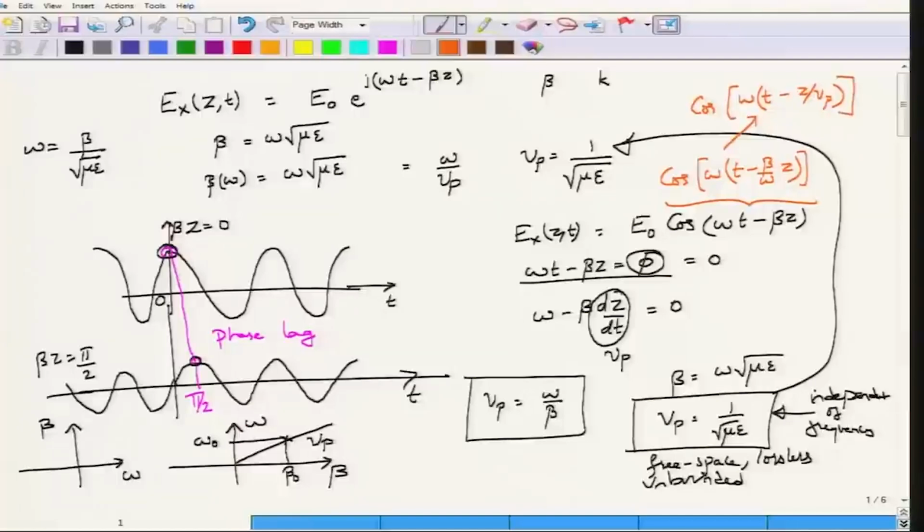This clearly indicates a travelling waveform with respect to time, but its phase velocity is Vp. If you remember your physics classes, this would be the wave equation for a wave that is propagating, having a frequency omega, having a velocity. At that point it was not specified what velocity you were considering, but this is actually the phase velocity. So, it is clear that the phase velocity happens to be independent of the frequency, and therefore, the phase lag that you would obtain would be the same for all frequency signals.